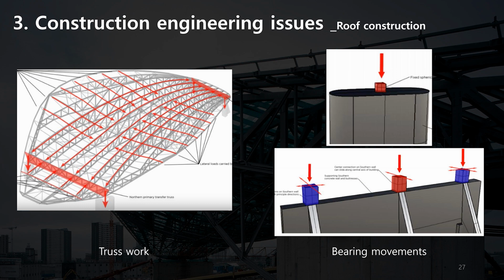This column-free structure was possible with complex truss structures. In the roof structure, the center fan truss carries load in truss action, spanning between north and south transverse trusses, which carry the load down to the supporting bearings on the concrete structure below.